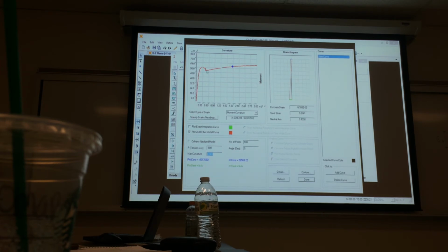This little curve you see here shows up in a lot of moment curvature curves. It's modeling the rebar a certain way that we haven't talked about. Don't worry too much about that. But as you pass this curve, you start coming back up, and you can see very clearly the strain profile in this section is changing. Okay. So you have, let's say, your compression region on top, you have your tensile region on the bottom. You can also see how your neutral axis depth changes as well.